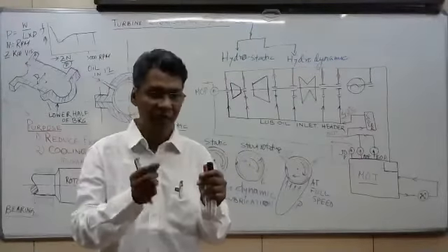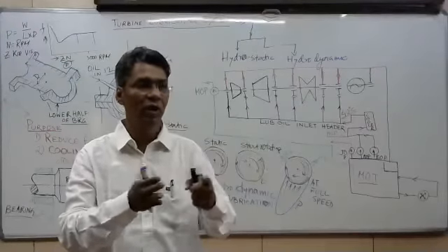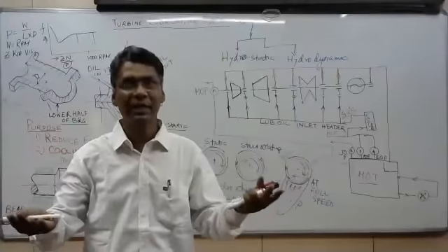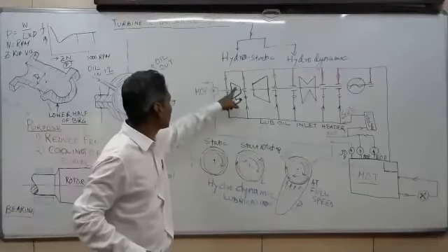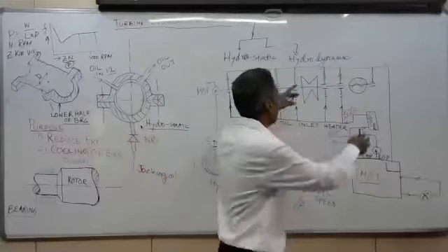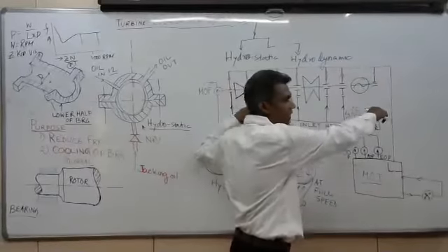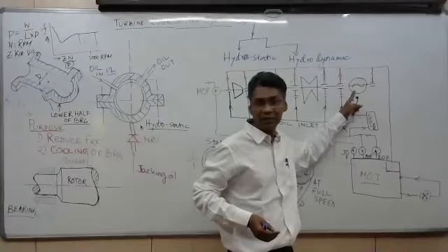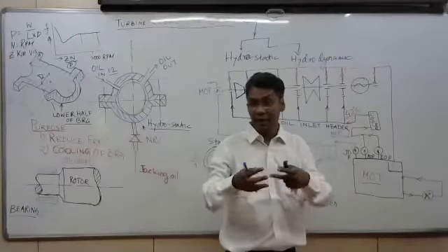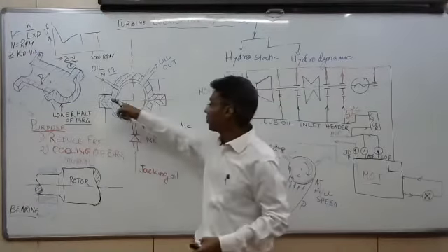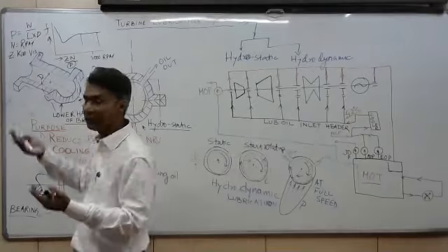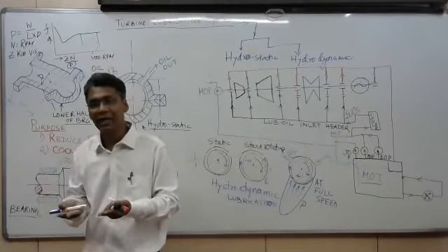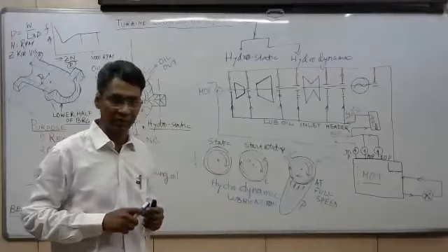So if we come to know the film load, we have to design the length as per the weight we are carrying between the two bearings. We know the weight of this turbine and generator, and the load distribution among the bearings. The generator is the heaviest part, so this bearing may have higher diameter and higher length. This projected area, that is D into L, is the bearing load-carrying area. The projected area we can calculate, and accordingly the bearing length can be calculated.